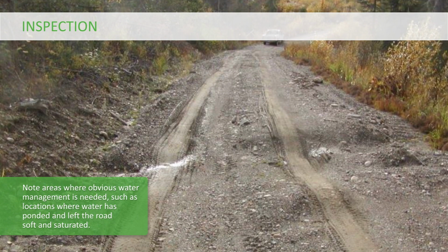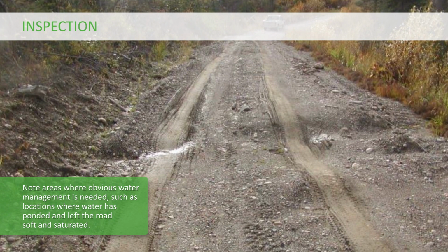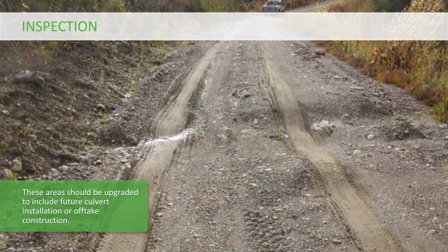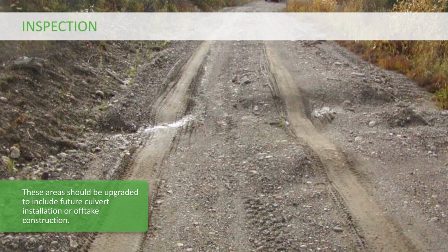Areas where obvious water management is needed should be noted, such as where water has ponded, creating soft and saturated road sections, and where there have been missed opportunities to break up long distances between culverts and offtakes.